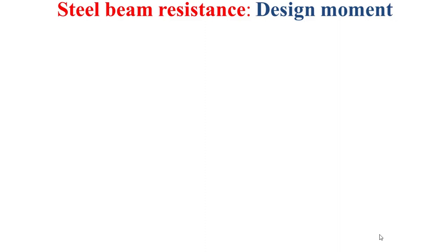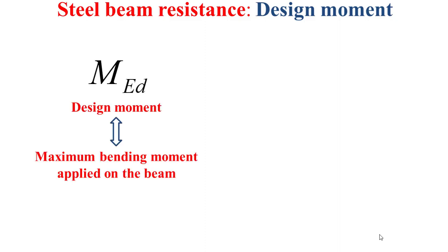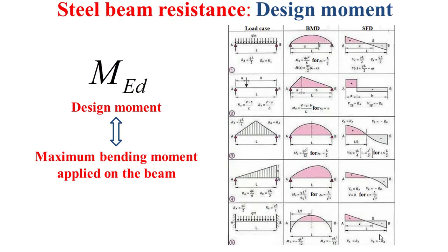Well, the design moment MEd is associated to the maximum bending moment applied on the beam, which is determined based on the bending moment diagram as it is depicted by the table that you see now in this slide. And as you can notice, the bending moment diagram depends on the load case applied on the beam, and there are other tables indicating more complicated load cases.